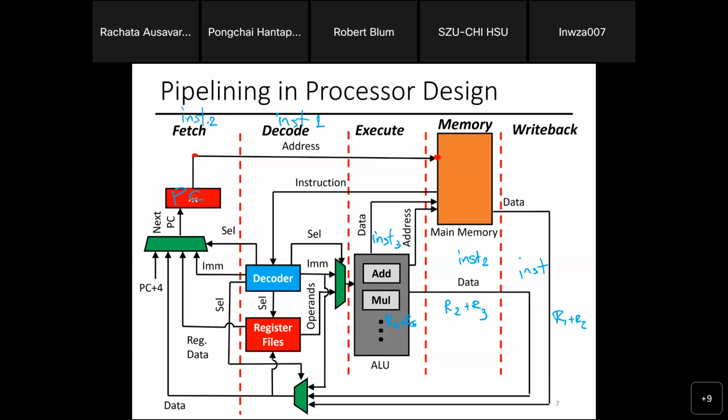Anything that can store data, except for a memory. Memory is too far. We don't use that. The register, right? So one of the ideas in pipelining is that for every single step here, we would add a unit called the pipeline register. It's not the same as the register file. These are things that the programmer doesn't see. These are internal inside the hardware, and designed to store this intermediate temp value.